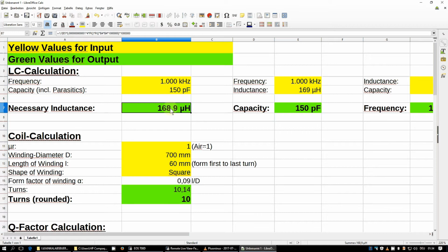We just want to check. We already know the inductance of our coil, which is rounded 3.4 microhenries, but later for getting an impression of the skin effect and the proximity effect, we should input the frequency. Let's say we want to use this Ferrite-Rod antenna for the short wave region around 5 megahertz.